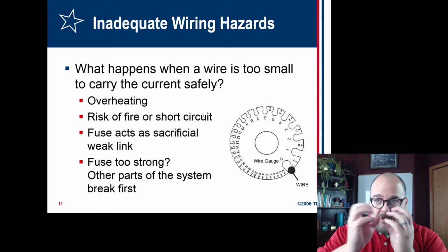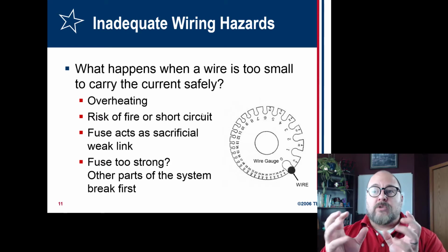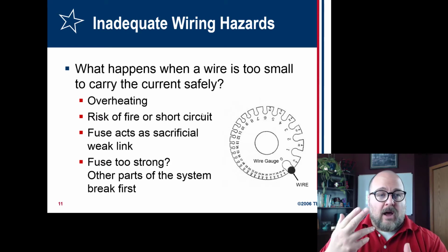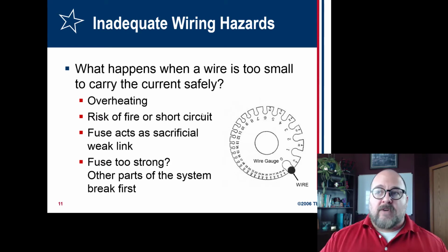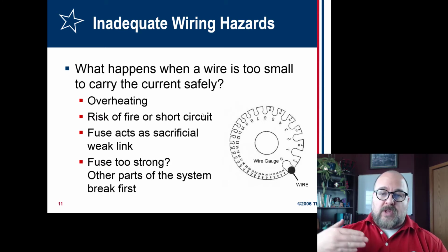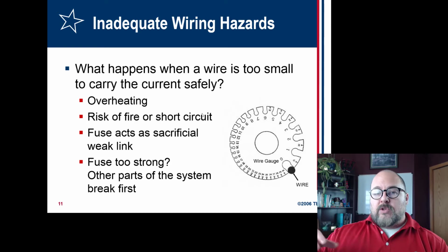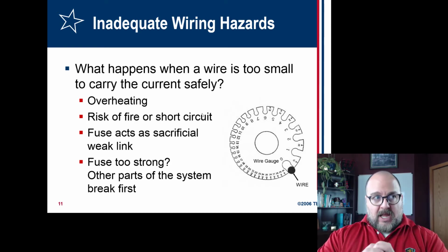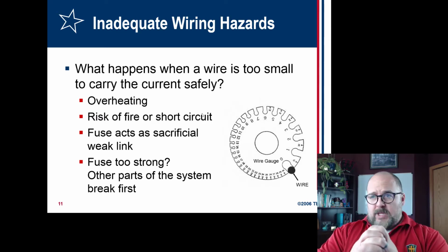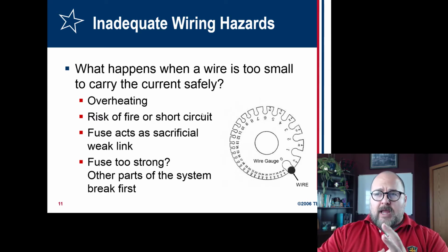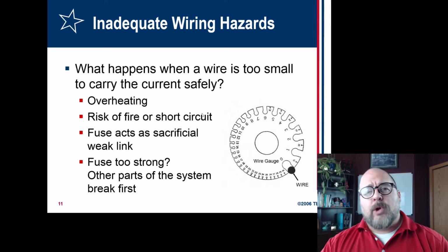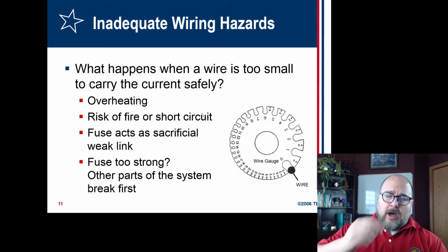And then when electrical components become exposed, they can arc, they can spark, they can cause fires, they can cause arc flashes. So you want to make sure that you're designing the system for what you need for power, and then you have an actual design component, either a fuse or a circuit breaker, that will monitor it.